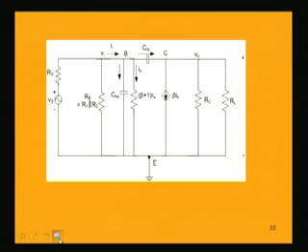Now, in order to analyze this circuit, we have a difficulty, it is not a simple circuit, because this shunting capacitance CBC is giving a problem, because it is now across these two points B and C. That means this capacitance CBC is not allowing the whole circuit to be divided into input and output circuits, as there is a part from base to collector.